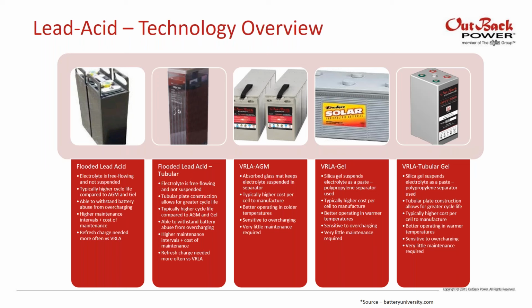So now we've gone over most of the technology from lead acid from a very high level view. Here you can see that we've listed them all out, with a couple of different characteristics for each chemistry or construction. But overall, the advantages of lead acid batteries: they have a pretty high cycle life. They have fairly low maintenance. Flooded does have some, but it's not too bad. They're 97% recyclable. They have a lower upfront cost, and they have a really well-supported infrastructure.